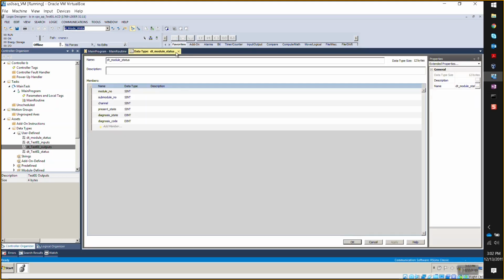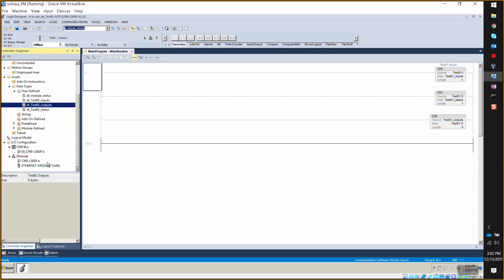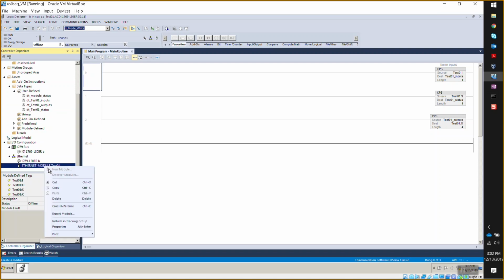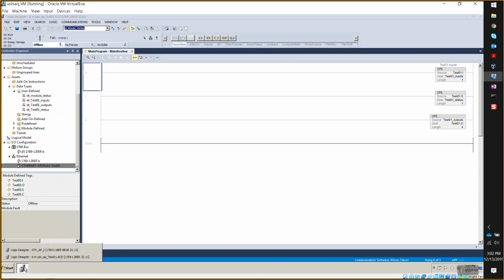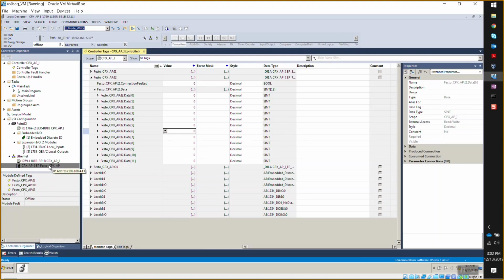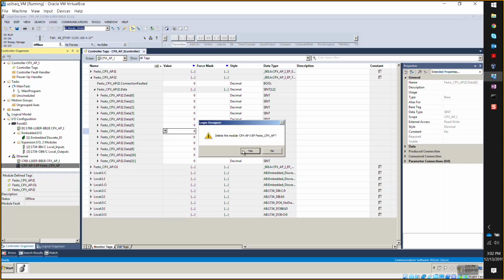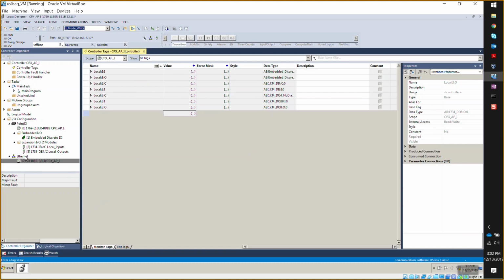Now we have to transfer this stuff over. We have to transfer this into the project that you're working on. Okay. Alrighty. So to do that, the first thing we could do is go to the Ethernet module on the left in the tree. Yeah. And then you can right-click on that, and then you can say copy. Copy. And then you can go to the other project, and you can paste. Okay. Well, I'm going to delete this one, because this is the one that we created with the EDS file. Right. So we can delete that. Okay. And now you can just right-click and paste. Paste. Yeah.